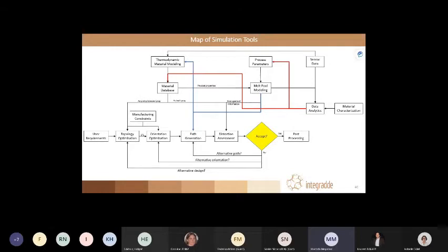So additive manufacturing, as any other manufacturing route, does have its own requirements and limitations. We take these into account during the design stage. Once we have the design, we can then move to the actual planning of manufacturing, which is orientation. How are we going to position the part in the machine? And how is the robot or the laser to be moved to create that body?